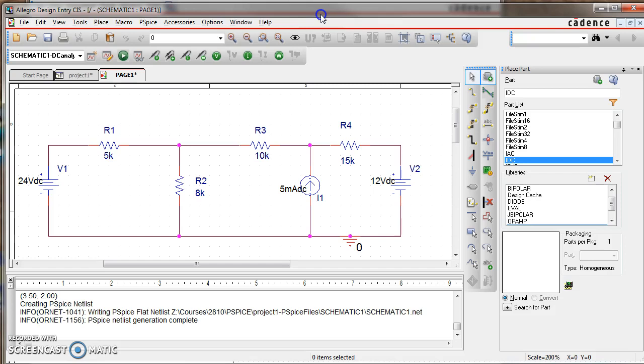Now, there isn't anything else obvious, so what we need to do now is look at the voltages and the currents in the circuit by clicking on these radio buttons. These are the items that become available to us because we did the bias point analysis. We can click on any one of these or all of these at the same time.